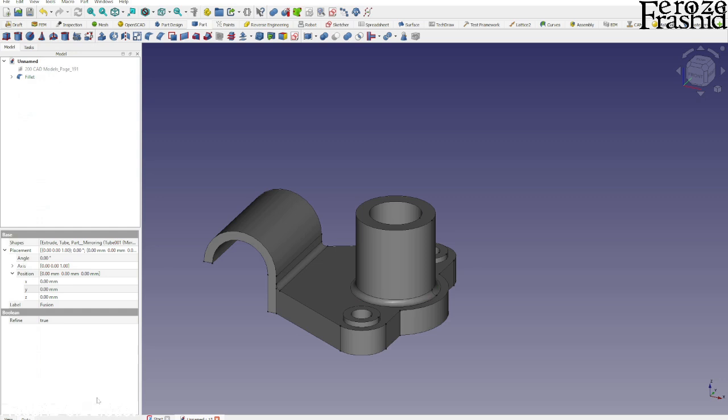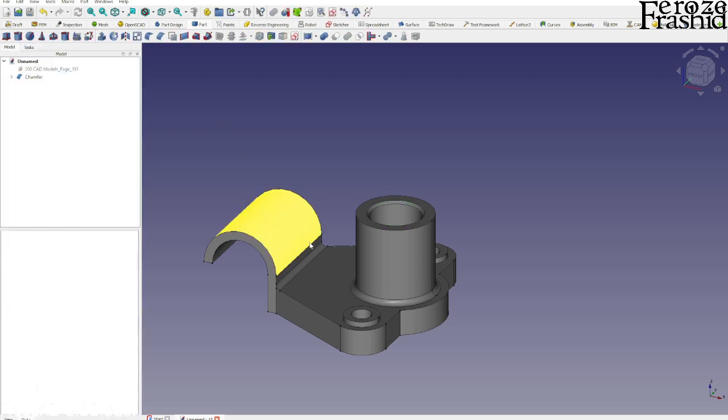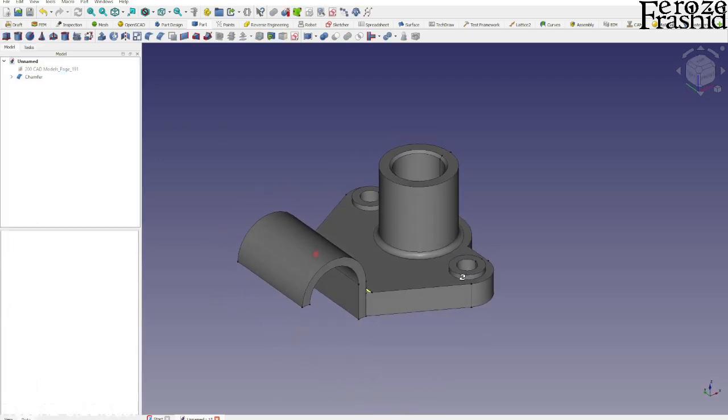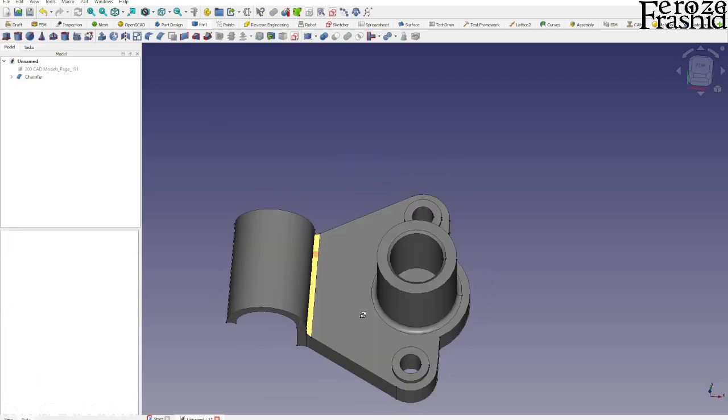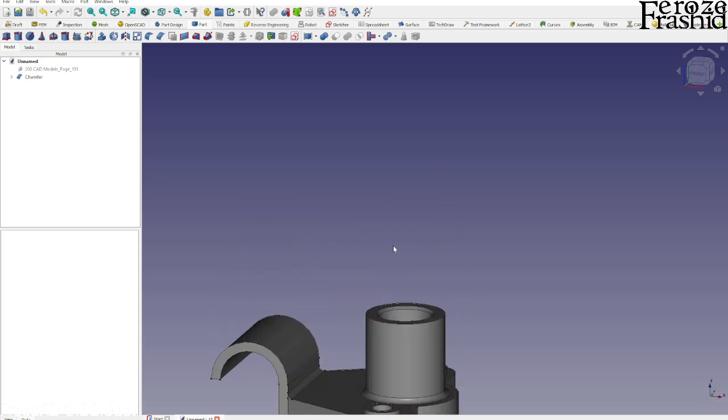Pretty cool. And then there is a chamfer up top, and that is, I think, 1 mm or so, yes. So there, 1 mm, and hit OK. That's our object. Notice how this hole did not go through.